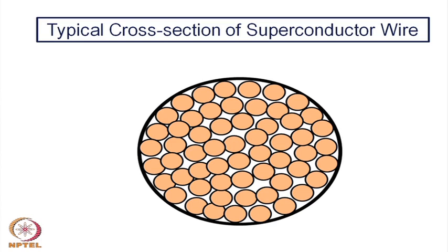So, this kind of system is used so that one can avoid thermal runaway at very high current densities. The current densities are extremely high. As you can see in the last slide, about 10 to the power 5 to 10 to the power 8 amps per square meter, which is a very high value. And therefore, when such high values of current are flowing through a cable, if there is a defect in the cable or in a particular wire strand, there is a possibility of heating up.